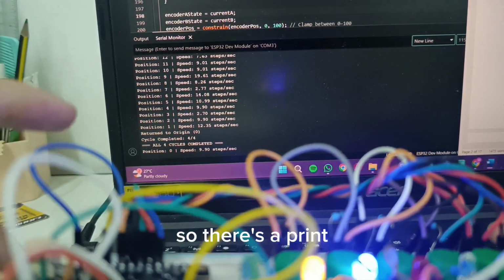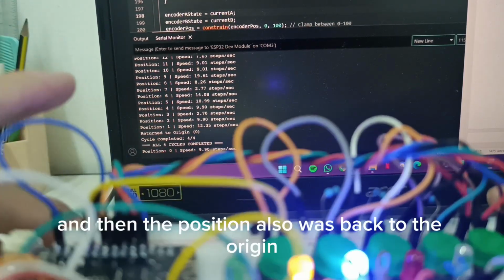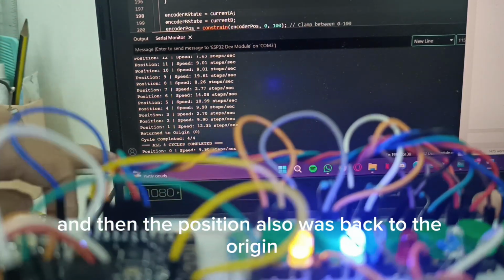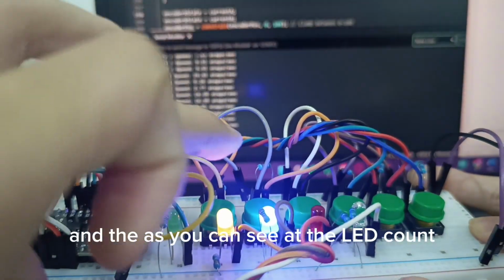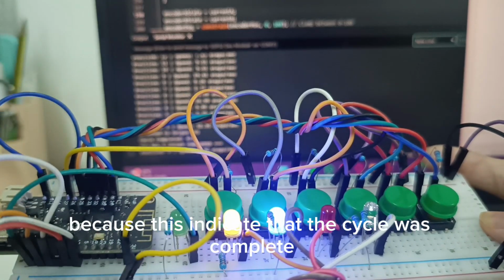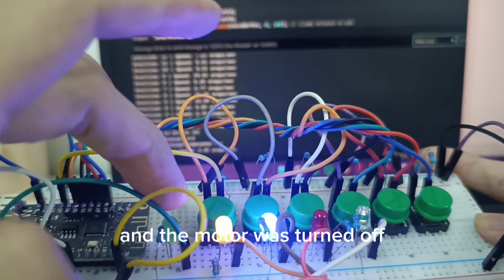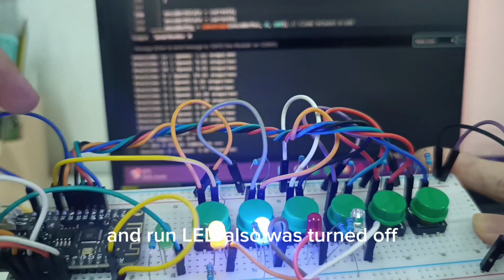There's a print in the serial monitor that says all 4 cycles are complete, and the position is also back to the origin. As you can see, the count LED turned on because it indicates that the cycle was complete and the motor was turned off. You can see the PWM turned off and the run LED also turned off.